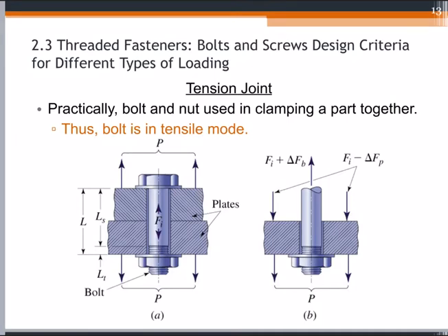As you can see from this figure, the plates will try to move outwards, upwards on the top plate and then downwards on the bottom plate. This will result in the bolt experiencing tensile force.